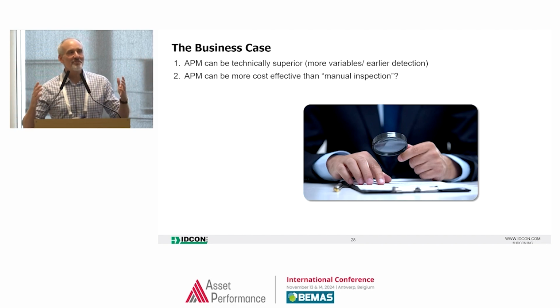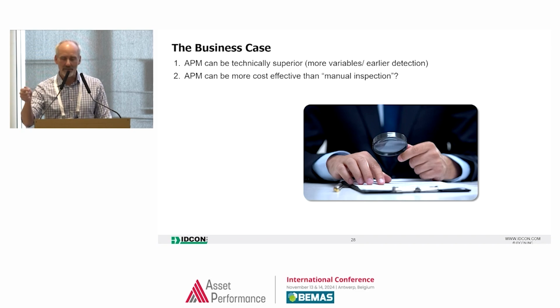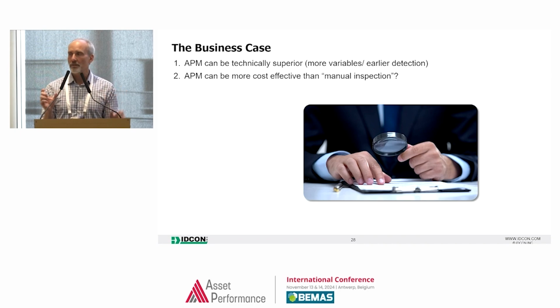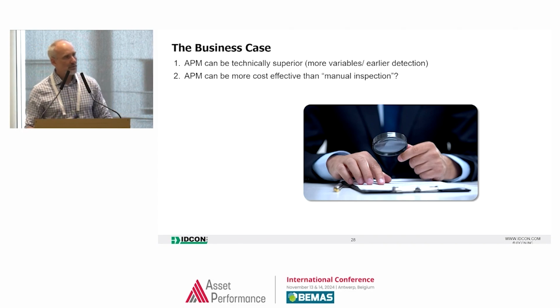I mean, all of you guys have some type of preventive maintenance, predictive maintenance in your plants, right? So to get the business case, you have to say, look, we have to compare it with manually having a guy going around doing vibration, look, listen, feel, smell, taking thermography readings, whatever it may be, versus automating it. Now the business case to me has been very hard. There are some, but to many here, it's very expensive technology. Some have less expensive technology, but then you're limited in what you can do. So some will take temperature, vibration, give you the software, give you the sensors fairly cheap, which is great. But then you're limited, you can't do a whole lot more than just those two, right?